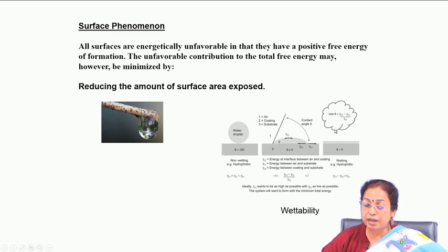A wettable surface has certain advantages, especially when you talk about materials for bioimplant application, which should be highly wettable. When you talk about a self-cleaning surface, it has to be wettable. On the other hand, for a high corrosion resistance coating, or a material which has to be applied in a water environment, with very high resistance to corrosion or erosion, it should be hydrophobic in nature. So, each and every phenomenon is driven by the surface energy. You can design the surface based on your requirement when and only when you know the surface energy value properly.